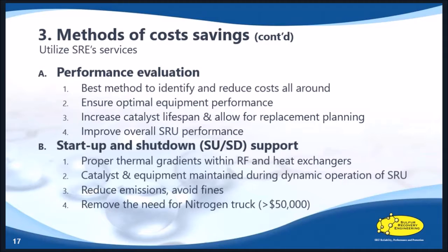Overall, at the same time, when you retain SRE for startup and shutdown support, you're making sure that you're not going to be paying for extra emission violations while you're going through the shutdown of a unit, ensuring that you're not having runaway sulfur fires, which will result in emission violations. You know, the regulatory body doesn't really look at if you're operating at steady state or if you're shutting down the unit for maintenance. They're just looking on a quarterly basis. Are you above or are you below your SO2 limits?